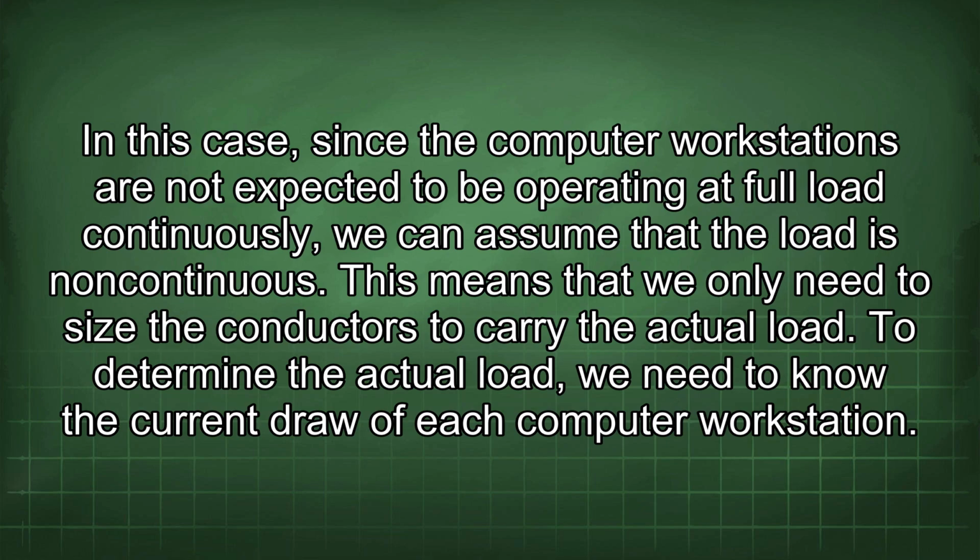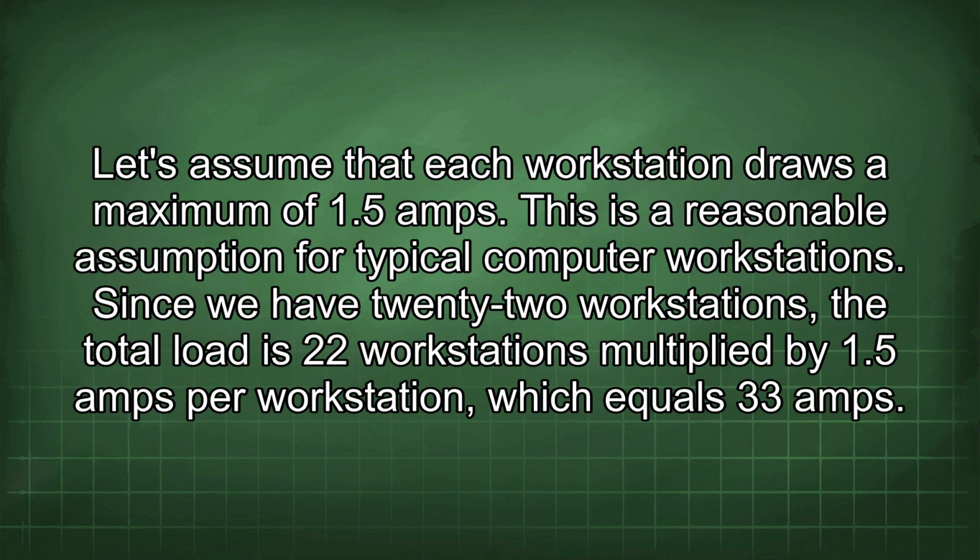To determine the actual load, we need to know the current draw of each computer workstation. Let's assume that each workstation draws a maximum of 1.5 amps. This is a reasonable assumption for typical computer workstations.